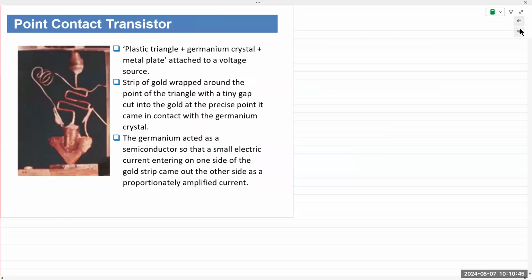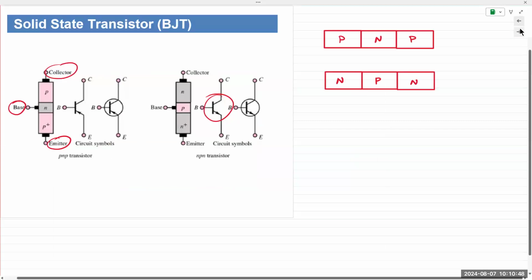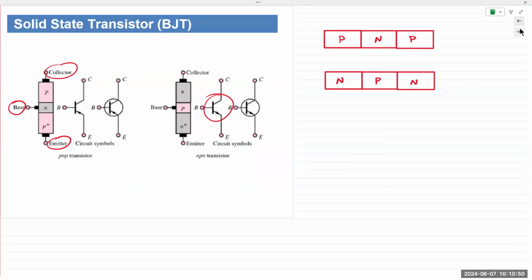And I introduced the topic last class. So just a brief recap. We looked at the PN junction diode, where you have a P-type semiconductor and an N-type semiconductor brought into close contact, functions like a vacuum tube diode, hence the name of that semiconductor device, PN junction diode. In a transistor, you actually have two PN junctions. So there is a PNP transistor and an NPN transistor. Both of those have a sandwiched layer between two semiconductors of the same type.